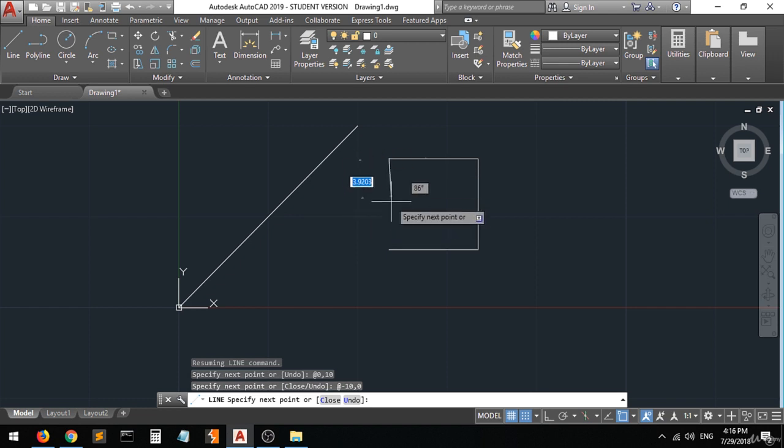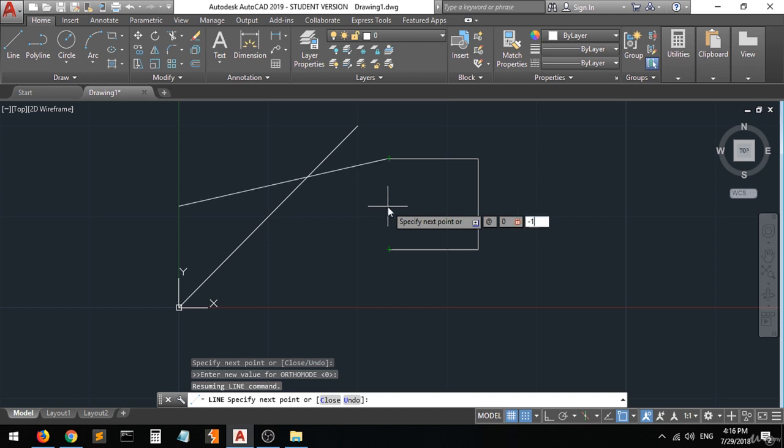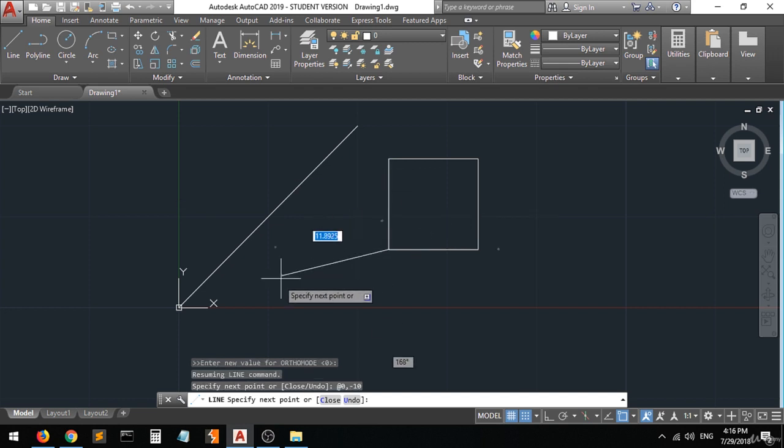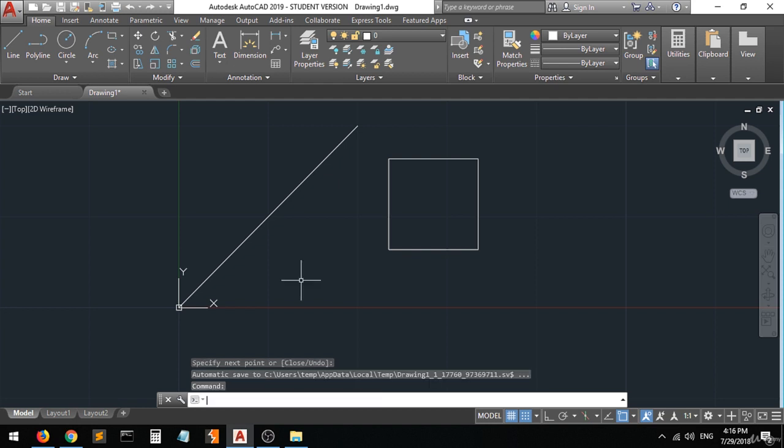Now you can do just this, put it for the endpoint, or you can do it as we did in the coordinate entry. Let's do it together. Shift to, we'll type the at sign. Now we're moving what? From this point down here, okay? So we'll do what? We'll move 0 on the x-axis slash minus 10 on the y-axis. Enter, and then press enter to end this session.